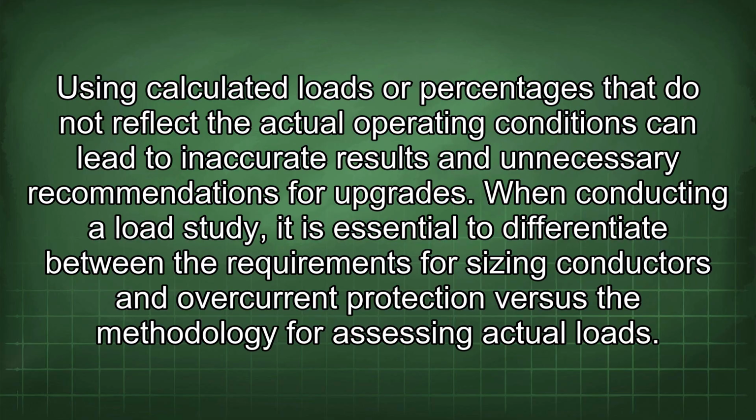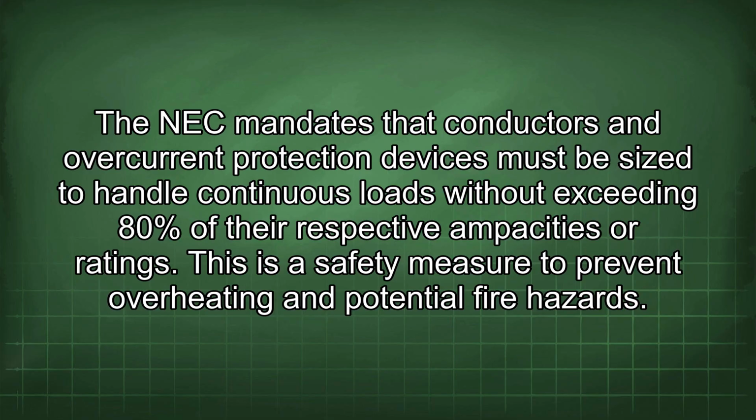When conducting a load study, it is essential to differentiate between the requirements for sizing conductors and overcurrent protection versus the methodology for assessing actual loads. The NEC mandates that conductors and overcurrent protection devices must be sized to handle continuous loads without exceeding 80% of their respective ampacities or ratings. This is a safety measure to prevent overheating and potential fire hazards.